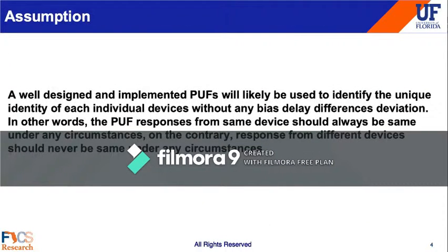Because of that, our assumption in this paper is that a well-designed and implemented PUF will be used to identify the unique identity of each individual device without any bias, delay differences, or deviations. In other words, the PUF responses from the same device should always be the same under any circumstances. On the contrary, responses from different devices should never be the same under any circumstances.